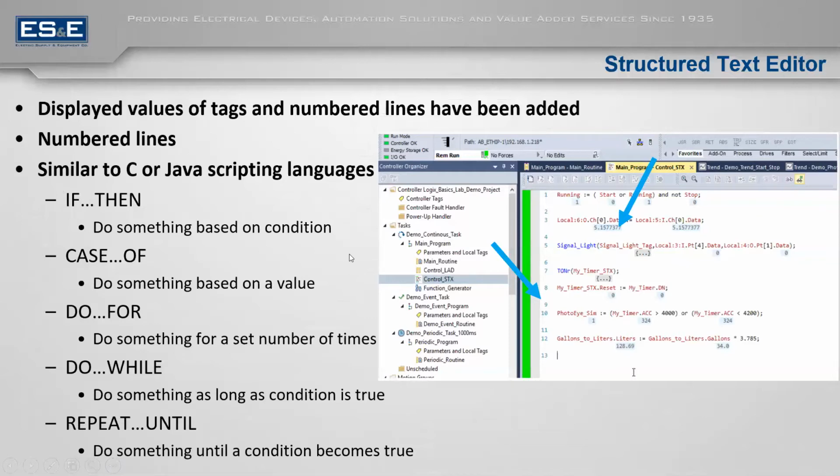Plus, it is now standardizing how they do it because Rockwell is embedded in there. You could execute an if-then statement on your own previously, but the format could not or may not match the next person who would do it. It's the same kind of concept that people don't like for ladder logic, that there are always 10 ways to skin a cat, so to speak. You have to know how that individual person does it, as opposed to when they create snippets or add-on instructions or something like that, where the code is always identical, and it makes things easier and more easy to track.